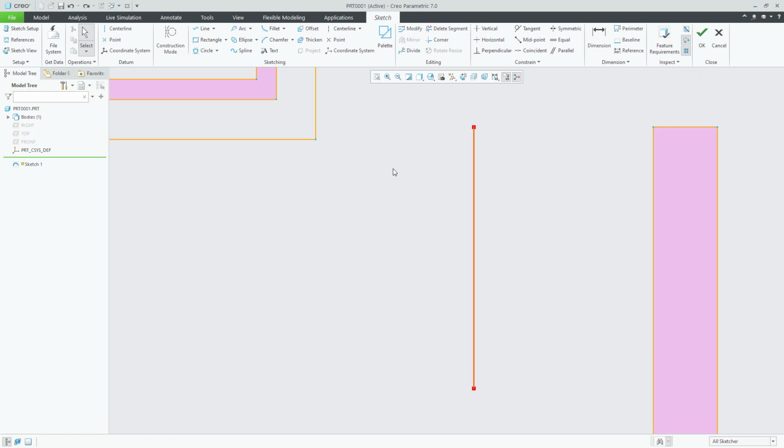So now our next command is thicken. Let's go to thicken, and here we can see we have a similar kind of window. So we have a single line over here, so the thicken edge will be single. And if we want to use any end caps, we can use these kinds of end caps over here. So let's go with the open one first.